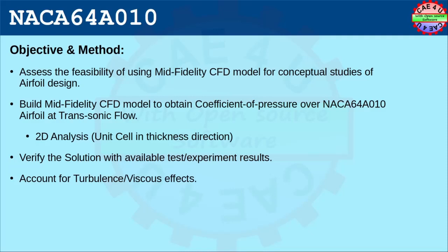For this simulation, we chose the NACA-64A010 airfoil, which is a symmetric airfoil. Since we are interested in section properties, we will adopt a 2D simulation. Nevertheless, we will compare the CFD results with available test results. For the present case, we will compare the coefficient of pressure.